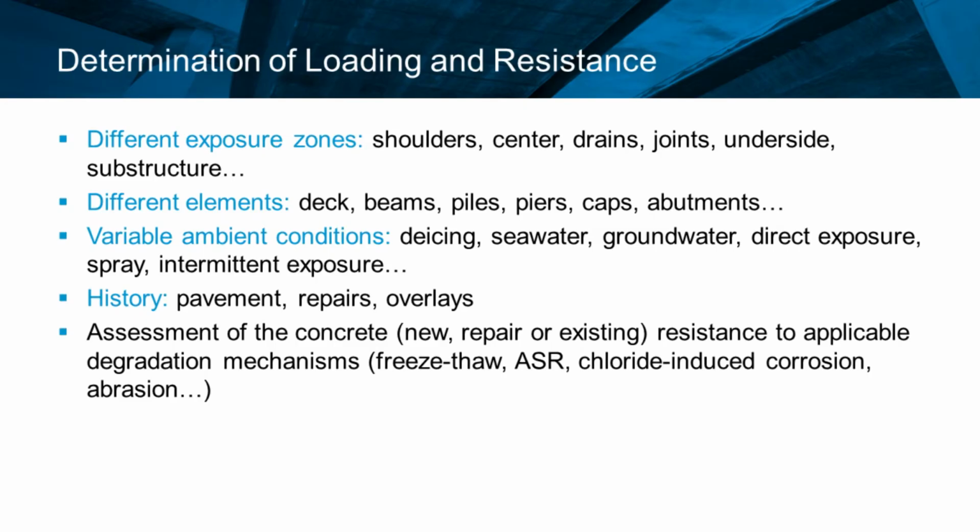The exposure conditions can be different for different elements, different zones of the concrete elements, so for the deck, the substructure. So ideally, we need to evaluate the different, or at least find the critical elements or the critical locations where damage is more likely to occur and be more frequent.